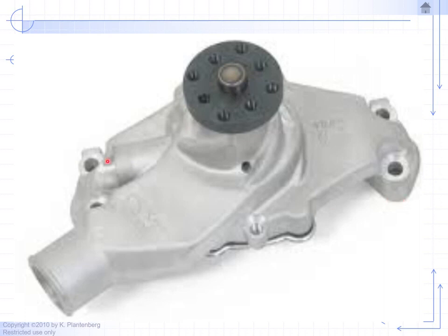So the bottom of these two feet you will machine so you have a nice smooth surface, parallel and coplanar to each other. And also you want the bolts, when you bolt it onto the engine block, to go in perpendicular to the engine block. So you're going to come in and machine these surfaces. These are referred to as spot faces. So before they were machined, you had a contoured surface here.